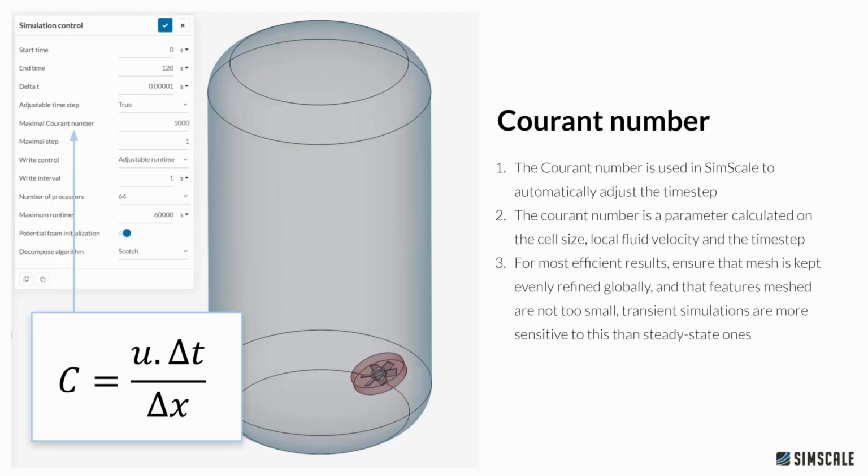Of course, the mean Courant number, we don't really want to go above 1, but certainly for those places and those areas where it is fast, the cell sizes may be small, such as in this case around that propeller, we could say that we can deal with a higher maximum Courant number, as long as we keep the mean Courant number to be approximately 1 or below.